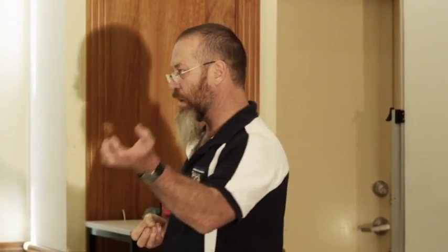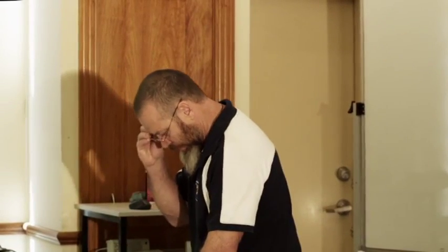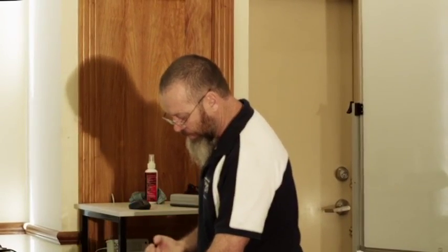And basically the connection, there's a whole series of tables that we need to go through and pull apart. But basically, all you need to do is, if I've calculated 2 kilonewtons of resistance for argument's sake, we need to go and find a connection that is equal to or greater than that 2 kilonewtons of resistance. It's as simple as that. And then, once you've selected the connection, what you do is you go back and just check that with your bracing.